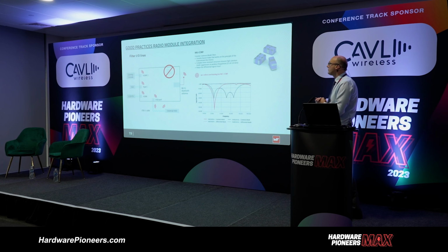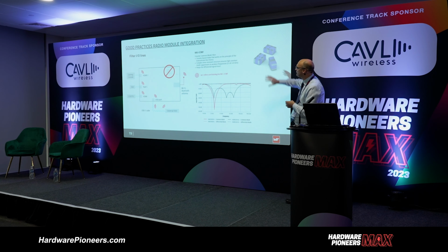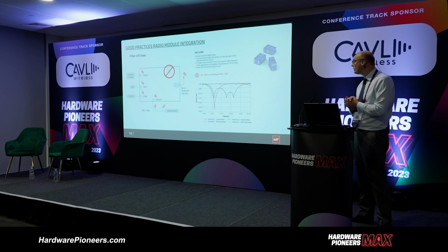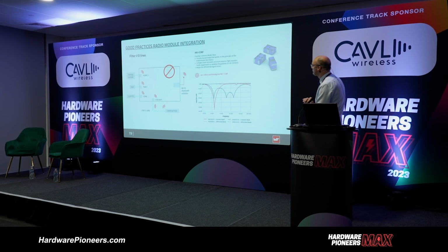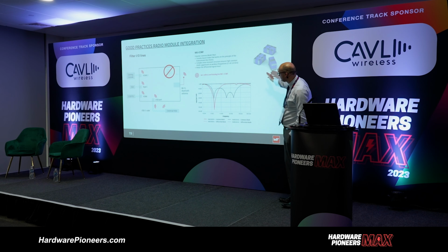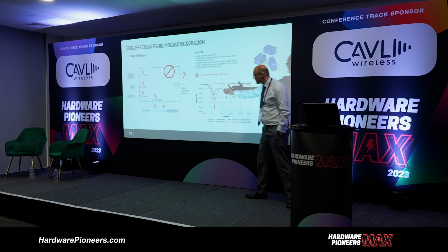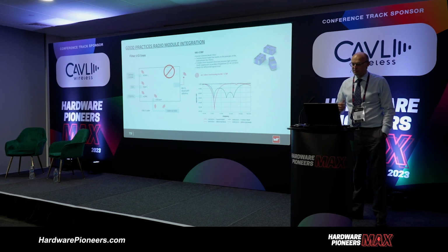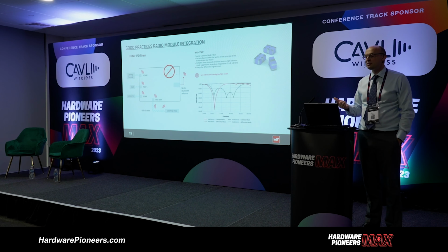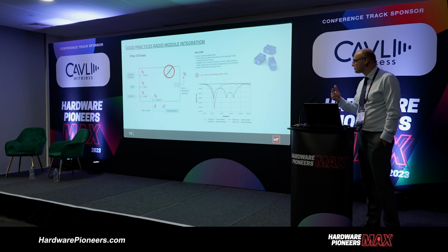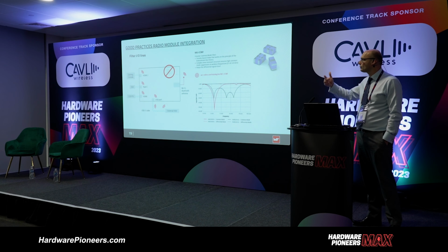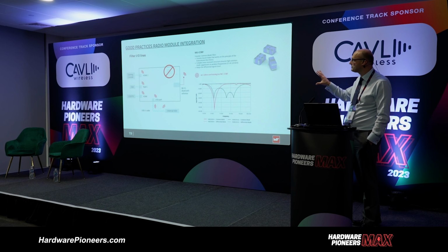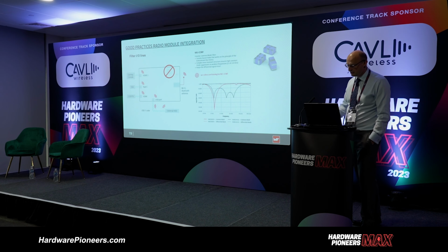So when it comes to I/O lines, there are certain products. Once again, we have a certain common mode choke. This one's a ceramic common mode filter that is designed to have high insertion loss at 2.4 gigahertz. This you can now implement on, say, the UART lines, the SPI lines, to protect the data, but to stop the intentional radiated signal off the antenna recoupling back into the RF circuit. So once again, we've seen problems with customers implementing pre-approved modules and not taking this into account.